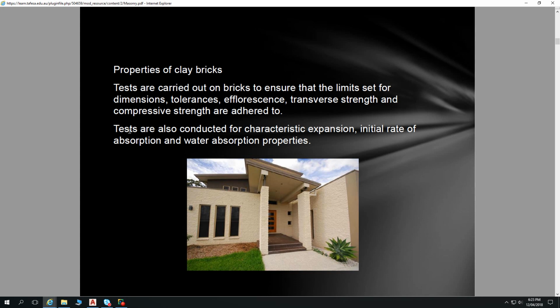If it's porous enough for moisture to get into and grab hold of those salts and bring them out, then you'll get efflorescence on the brickwork. Unfortunately, I can't show any examples of that on the bricks that we've got, because they're not in place. They're not getting wet.